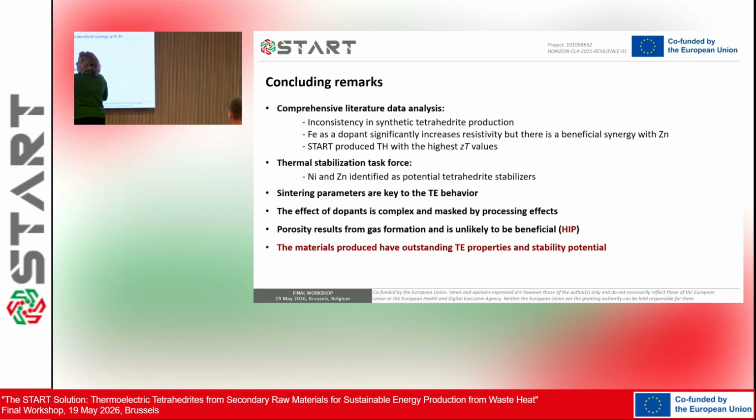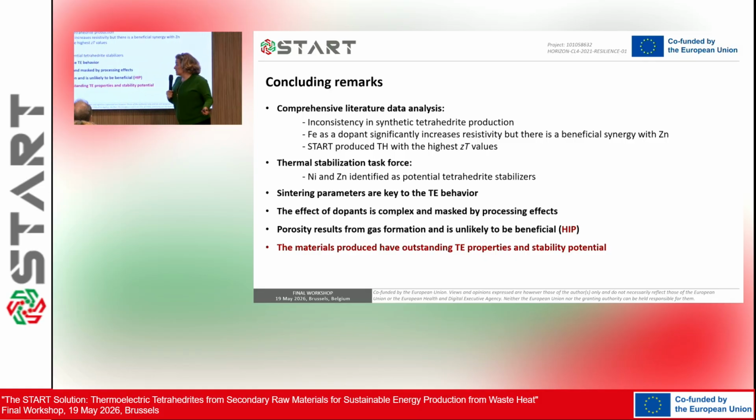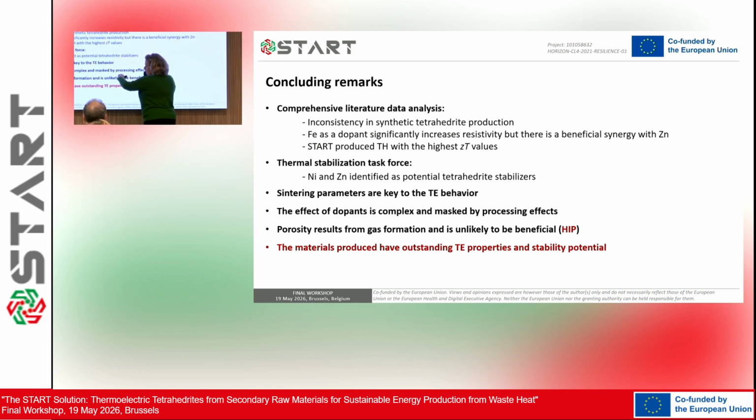The sintering parameters are key to the thermoelectric behavior, and this needs to be investigated further. But the most important conclusion is that the effect of doping is quite complex and masked by the processing effects. The porosity, which results from gas formation, is unlikely to be beneficial, because of what you find in the literature in terms of the mean-free path of phonons in tetrahedrite.